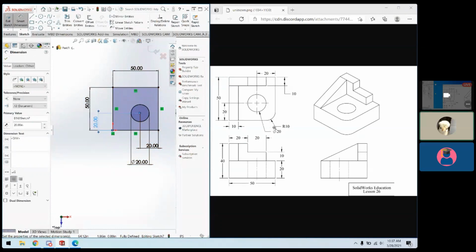So to do this, there are multiple ways we can do this radius or rounding, right? So we can first do it in the sketch section, draw it out and then extrude that as a rounded edge, or we can have it a solid edge and then we can round it after extrusion. And we will talk about the second method in the future CAD workshops. It's going to be CAD workshop number 2. But for now, I'll just show you the sketch option, which is a sketch fillet.